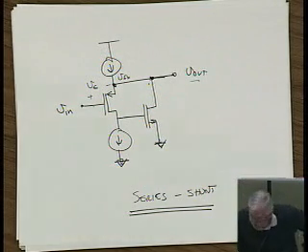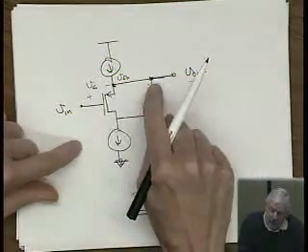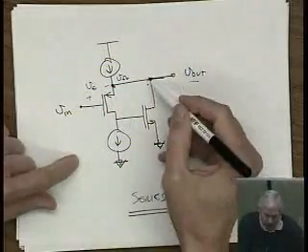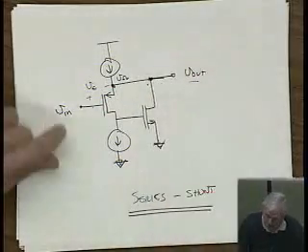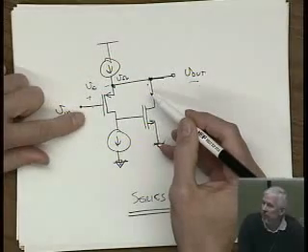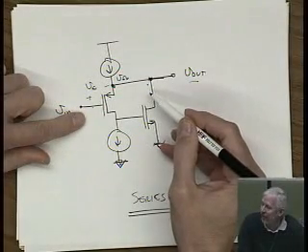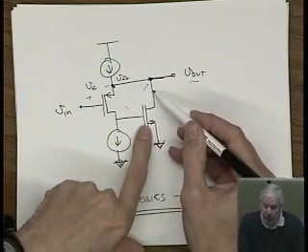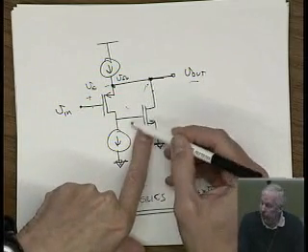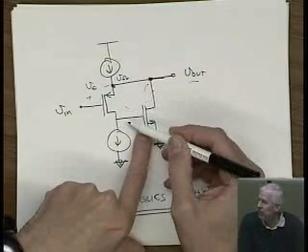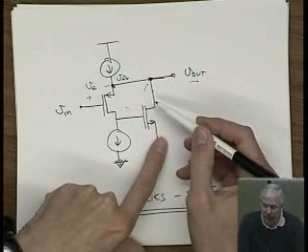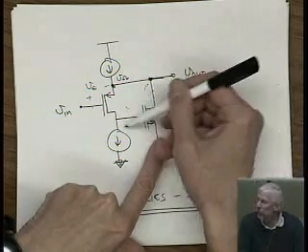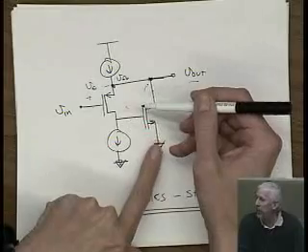Your question was, how did I know it didn't go through? Well, take a shot at it. Well, where do you think it might go? Go down through here somehow? Well, what's the feedback from here to here? What's the transfer function in this direction? None, yeah. Take the none. You don't go backwards through a transistor from drain to gate, right? So there's essentially no signal hardly at all doing that, right?